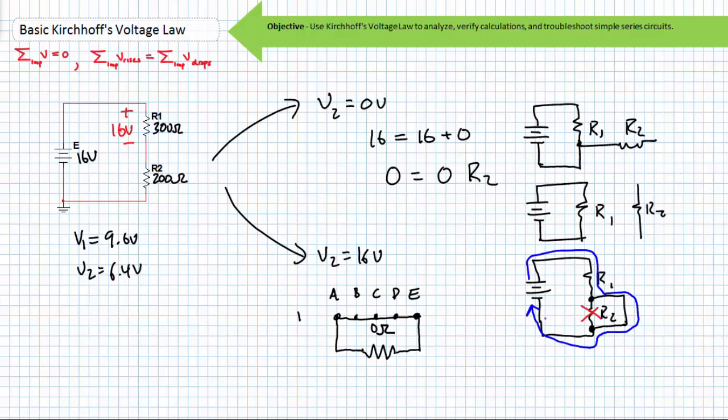In this case, the source is only seeing R1's opposition, and all voltage will be dropped across it. I must reiterate, components go node to node on a protoboard, and at no point would I ever place 2 leads of a component at the same node. It doesn't make sense schematically, nor does it make sense when looking at a protoboard at the nodal level.